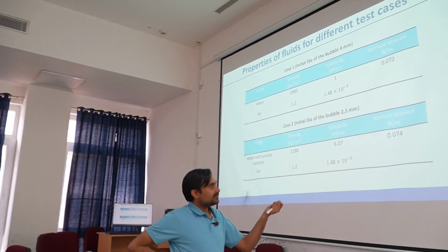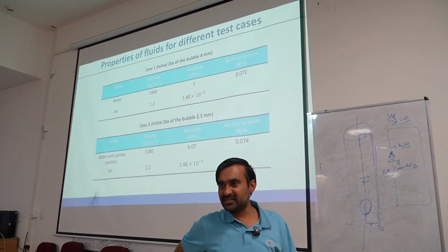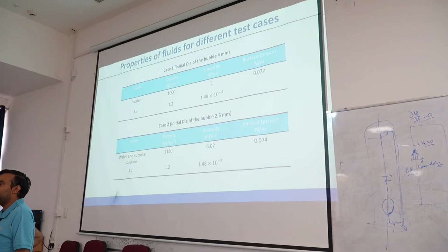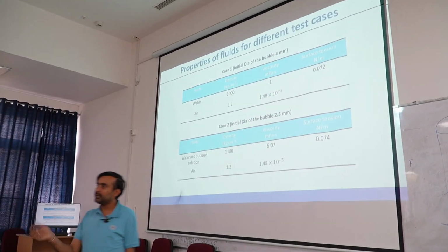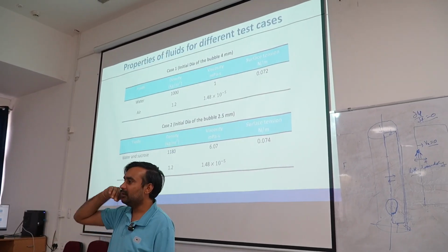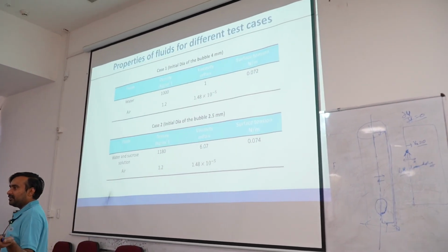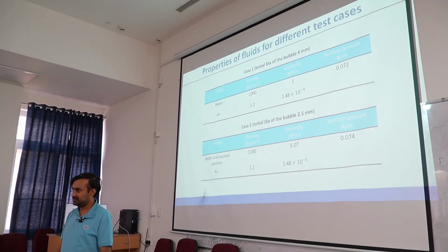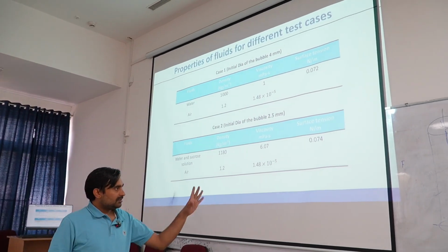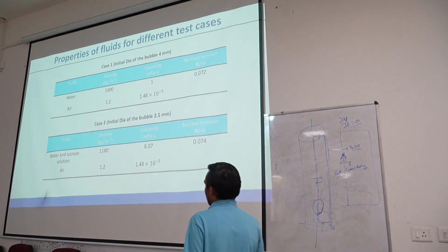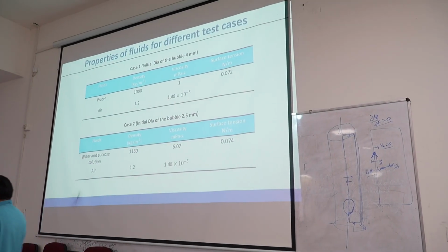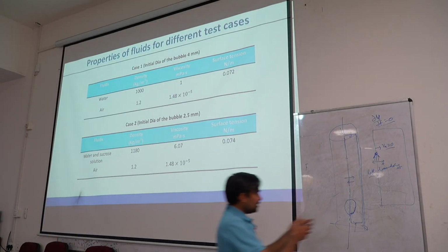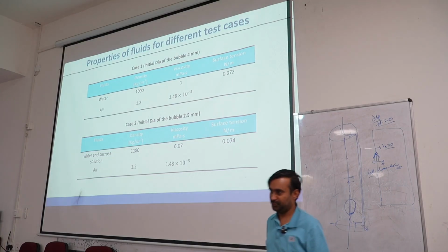The way velocity is symmetric, in a similar way, pressure and all other parameters have to be symmetric, then only will my situation be purely axisymmetric. So, I cannot say that one of the field variables is meeting the requirement of symmetry and other variables are not meeting it. If this is the situation, then I cannot say my situation is purely axisymmetric. Is this point clear? So, this will be the slight change in boundary conditions. So, now it means that if we have to make our simulation domain, we have to simply make a rectangle as our simulation domain.